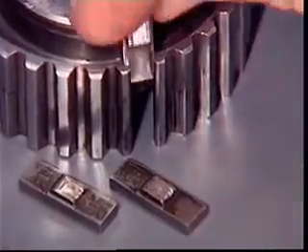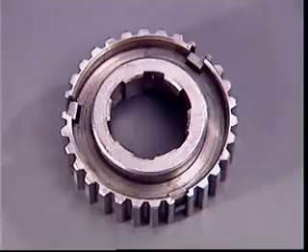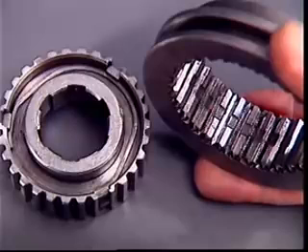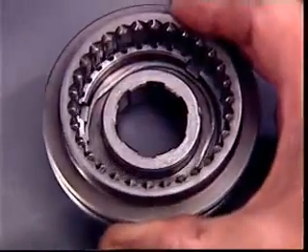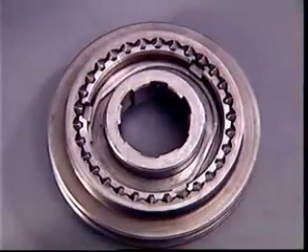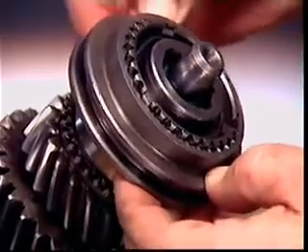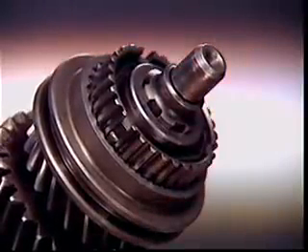3 metal inserts with a ridge fit into slots in the hub. A radial spring at each end holds them out so that the ridges locate in a groove inside the sleeve and hold it centrally on the hub. When the synchronizer is assembled, the hub is splined to the main shaft, and the engagement sleeve is splined to the hub.